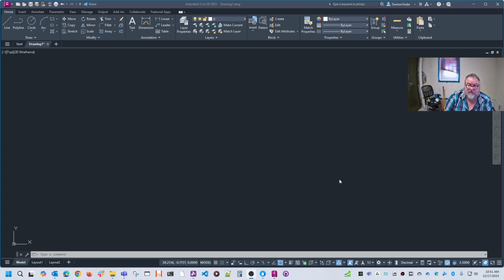Okay, well, let's draw a manhole. Now, how do you show a manhole? Well, a manhole, it's typically about a 4-foot diameter hole in the ground. Okay, well, if I do a 4-foot hole in the ground, but I'm working at 100 scale, that's going to be a pretty small hole. If an inch is 100 feet and I'm putting in something that's a 4-foot diameter, that's pretty small.